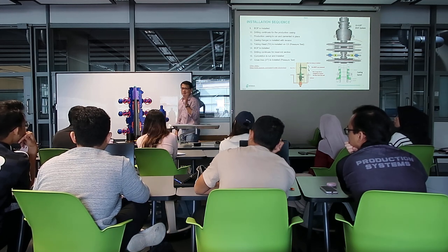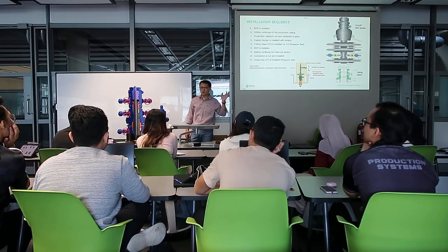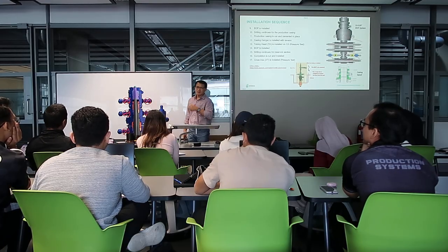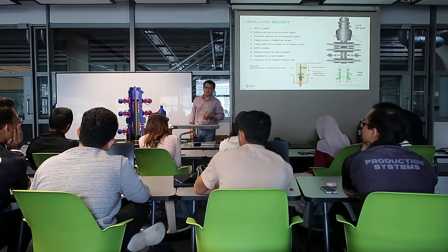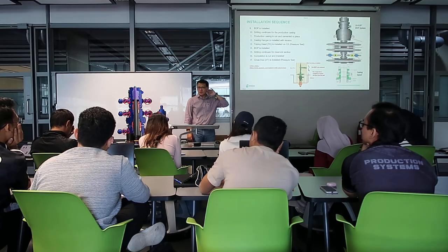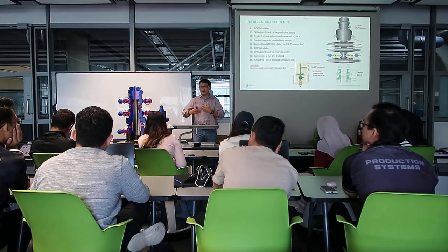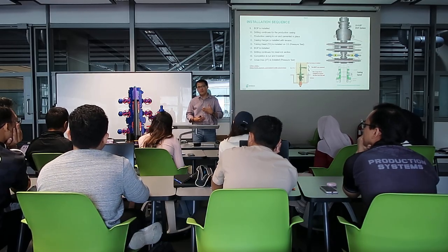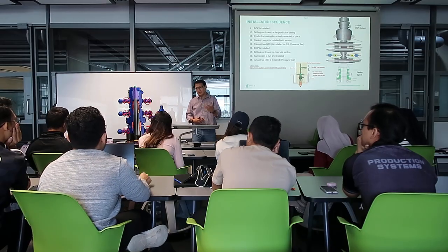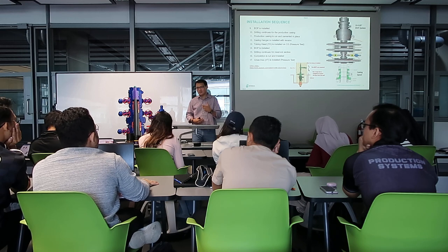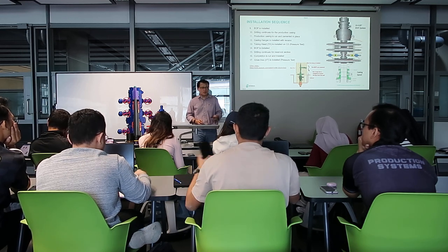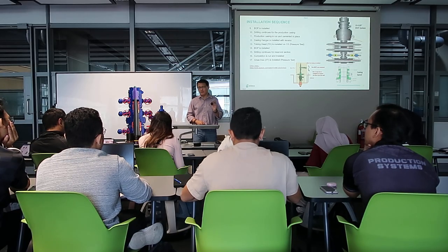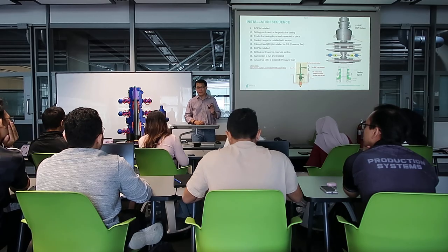But the design is slightly different. Just now is the real basic and base view. I think when we introduce more on the wellhead components, then we can have a better view. But the installation sequence there is just really to get you the rhythm. When we install wellhead, then when we drill, then we run a casing, then we cement, and then house the hangers and all this install in place. There is no major hanger except like the tubing hanger you see. Tubing hanger is really like major hanger type. Okay.